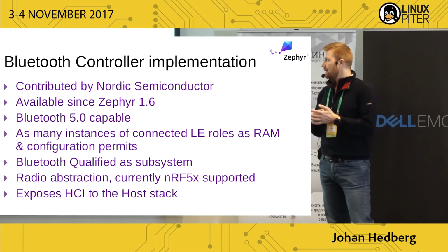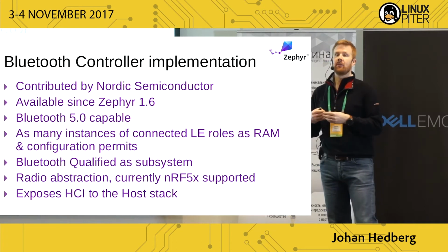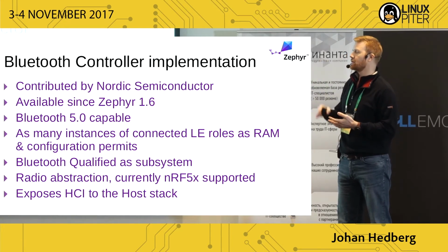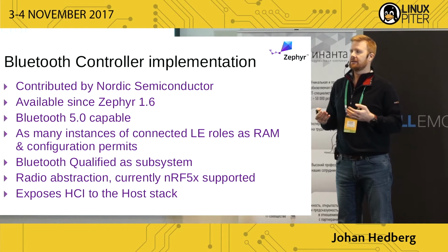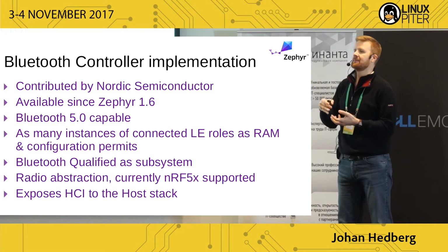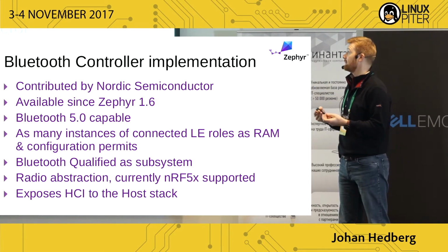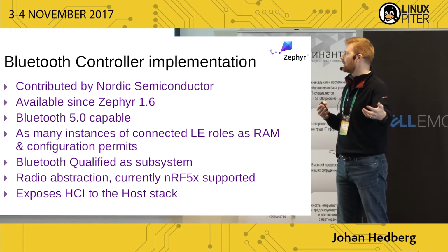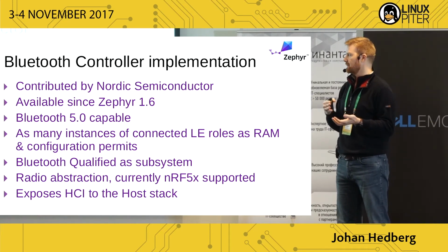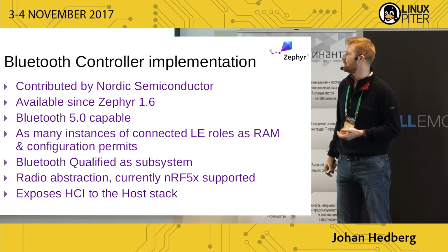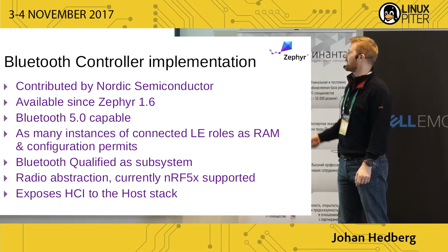And the interface, of course, that the controller exposes is HCI. As I mentioned there in the first slide, that sits between the controller and the host. Now, whenever you have a product where you have the controller and the host running on the same CPU in the same address space, the Bluetooth specification doesn't require you to have HCI. But because that's what we use in Zephyr anyway, if you want to talk over a physical transport to another controller, it was the most natural thing to choose for the host layers and the controller to talk to each other, even though they're sitting in the same address space, even though there's no physical transport as such.